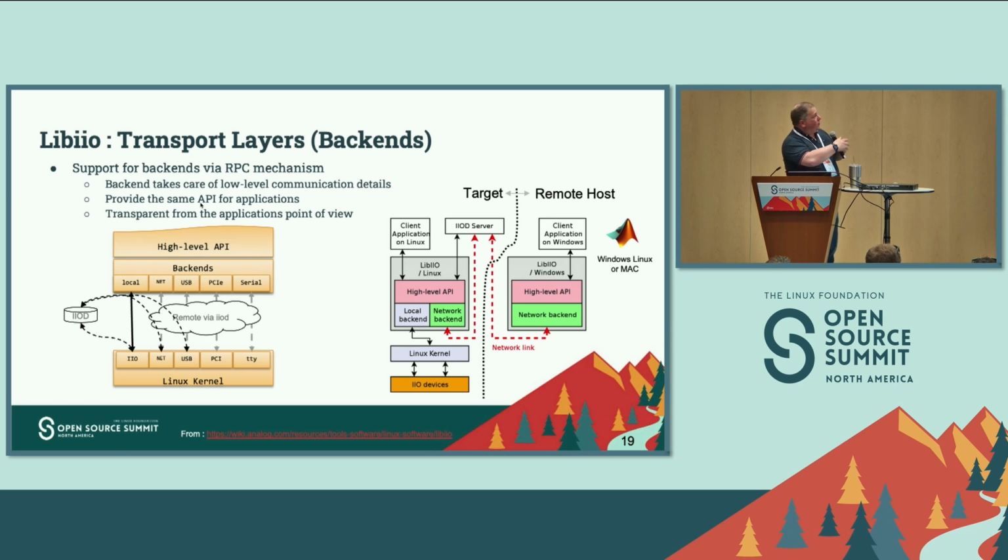And the remote host side can be MATLAB, can be Python, it can be Julia. It should be meeting your algorithm engineer where they already are. You shouldn't have to learn a new environment because you want to program or capture data. Somebody interested in doing Kalman filters is not interested in doing it at low level on your embedded target. They want to do it in MATLAB or in a higher level of abstraction like Python. And this allows them to do those kinds of things.